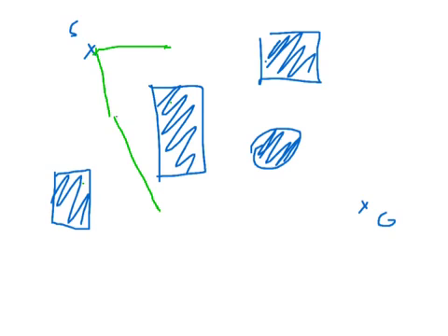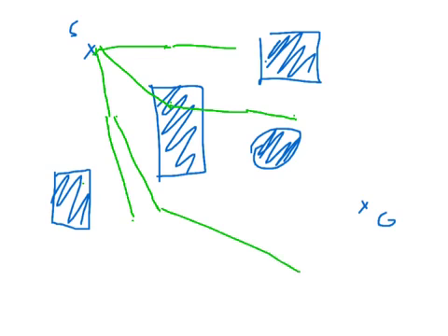It turns out, however, that for some problems, doing something called lazy collision checking is actually preferable. In this case, what you would do is you would actually draw a path even though the point is in collision and continue your search until you find a goal. That would look something like this. So we would start connecting things. Let's say we have some goal biasing here. So actually this is our path.